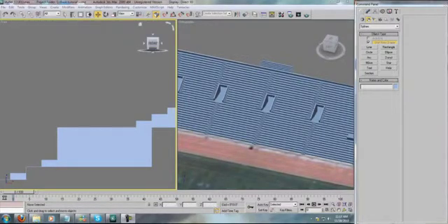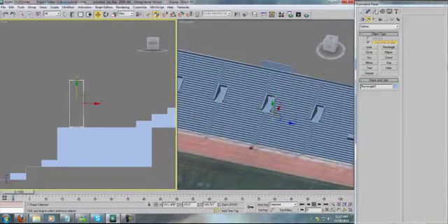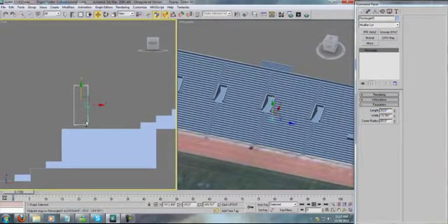I looked up online and it said that handrails were typically 3 feet. I want to double check that though. So I'm going to create a rectangle, set the height to 3 feet, snap it to the floor here,